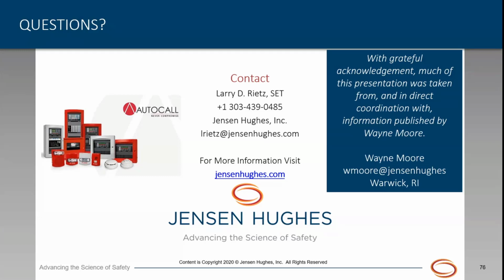Now, sometimes that is done. You also might have, once you're in the zone, again, you can transition to normal cable and go to normal cable to, let's say, a control panel that's not in a rated room and then land that. But again, you got to look at these scenarios. It's kind of based on the specific scenario. But letter of the law, per the question, the answer would be no.